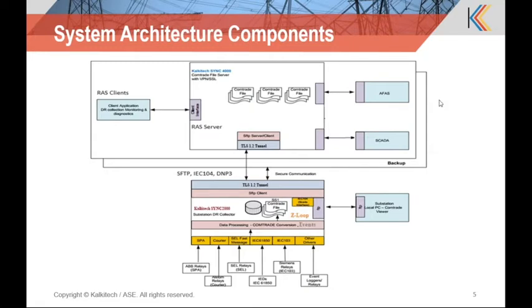Plus, in the Sync 2000 itself, the loop impedance algorithm is available, and using this algorithm, we calculate from the Comtrade file what the impedance value to the fault is, and depending upon the impedance value, we put it in the file also containing full details. Plus this impedance value is available to map to the corresponding protocols like 104 and DNP3, and the same value is sent to the center to do the complete analysis. So these complete loop impedance values are pushed to the central system for doing the analysis.